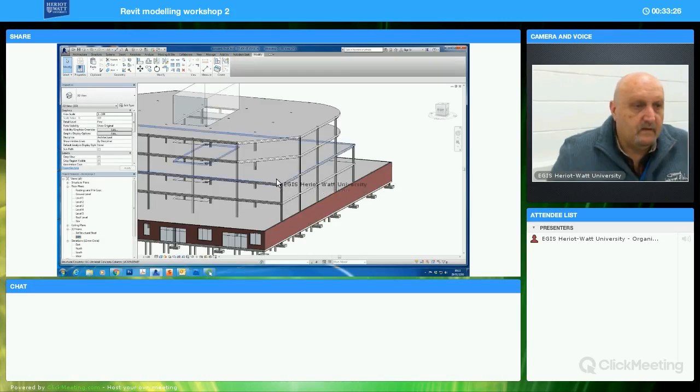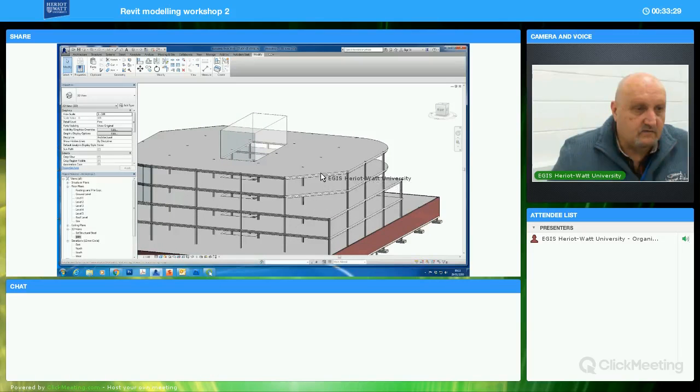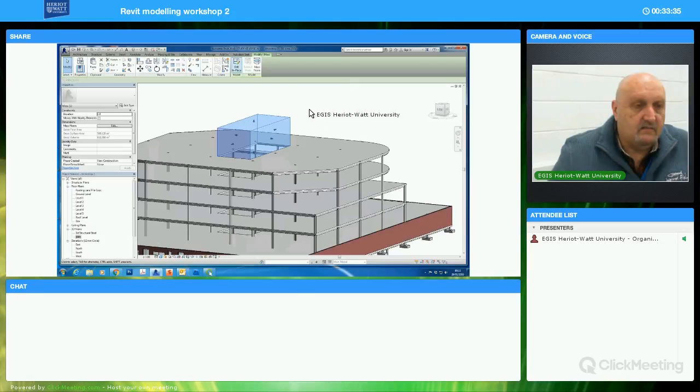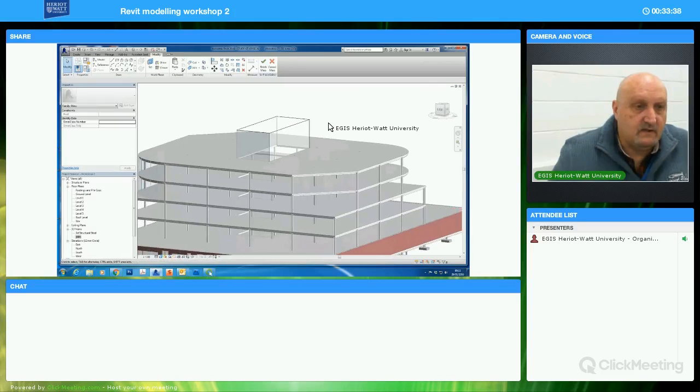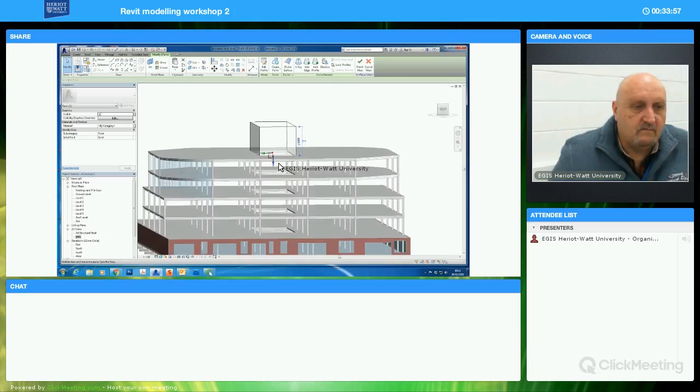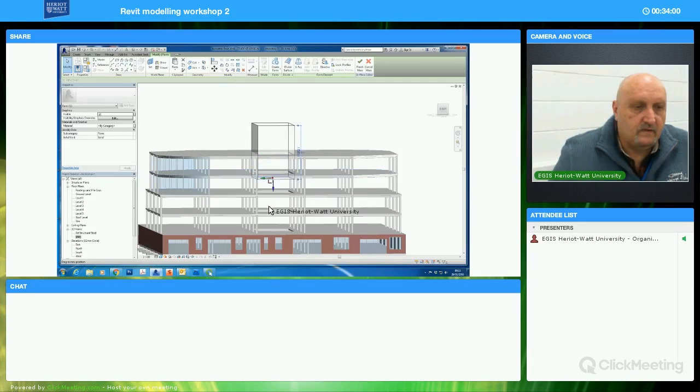In 3D, you'll see this kind of translucent, weird 3D object appear, and if I select it and edit it in place, you'll see I can do 3 things. I can edit it in 3 ways, kind of immediately. I can edit the corners, which I'm not going to do. I can edit the edges, equally I'm not going to do that either. And the final one is I can edit the faces, and that's what I'm going to do with this one. I'm going to choose the face on the underside, and I get a cursor appearing, and this time I want to drag it down. I want to drag it down until it stops at the ground, at level 1 floor, not the ground floor, level 1.